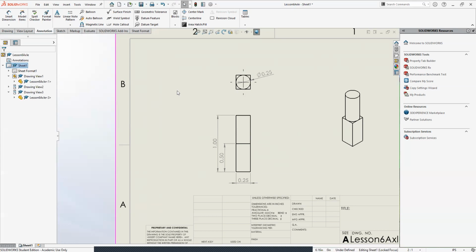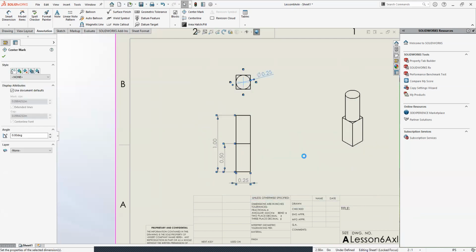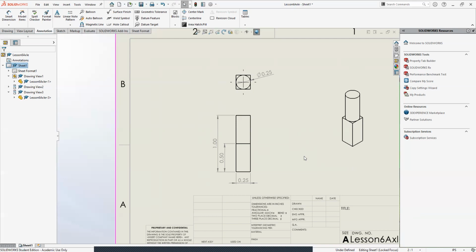Yeah, generally what happens is, let's say you make a part. These drawings are really for people making them. So if I need this axle made by someone, sure, a lot of times in robotics we're dealing with things that we can buy. But let's say we needed someone to just make a part for us, whether it's on the CNC or maybe they need to mill it, something like that. Someone needs to machine a part. These drawings are basically a way for you to print out a piece of paper, give it to them, and they can use that as reference when they're making it, instead of having to have a laptop open with your drawing and checking all your dimensions, or a laptop open with your part.